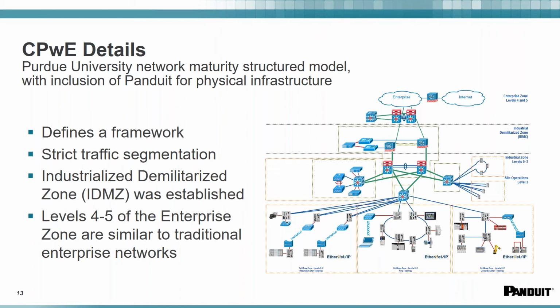And if there is segmentation of the network, it will show you those different segments to be able to isolate traffic and so forth. And it's built on the ISO model, the 7 layers in the ISO. So the first 2 layers at the bottom are where you have a lot of control systems. This is the layer where you have I/O and control devices and ring networks and star networks and other things.